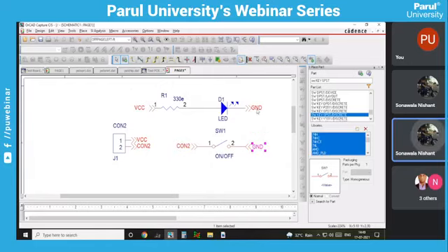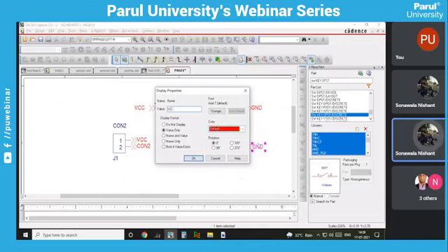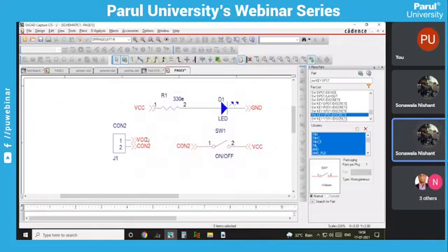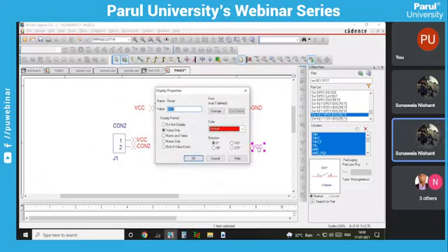This is ground, this is GND, so it is internally connected. If I write here VCC, it means VCC is directly connected over here, and this ground pin is not connected with second number pin. It connects with VCC directly. So whenever you design, you have to keep in mind that whatever off-page connector and whatever the net you are using, you have to mention here, right?